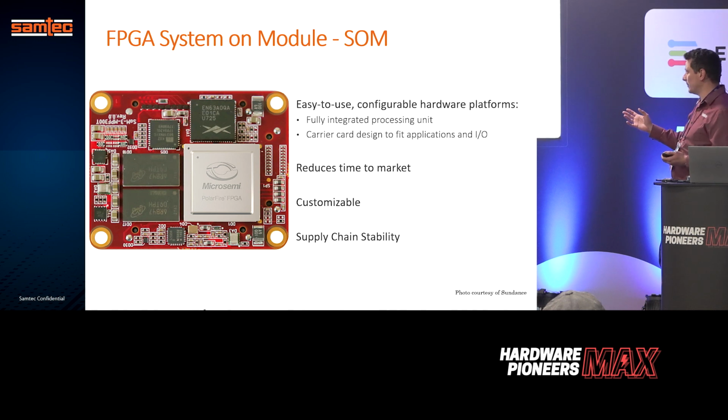And in this case, in most of the system on module that you will see in the market, there is normally a Samtec connector attached. So one of the biggest questions on system on module is standardization. So many people will have their own footprint with their own connectors, their own sizes to fit the applications where they start the design on. But there is a push in the industry to try to standardize it.